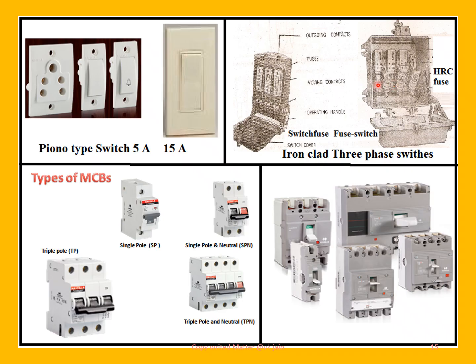So these are the HRC fuses, and these are the contacts where these contacts 1, 2, 3 will sit here when the switch is closed. And earlier we were using fuses like this, porcelain base rewirable type of fuses. Now here also fuses are deployed. On a slight short circuit the fuse gets blown, and then you have to replace it. That is a costly affair.